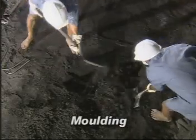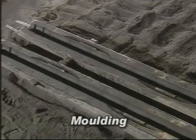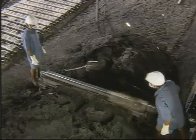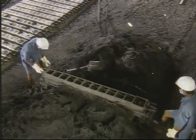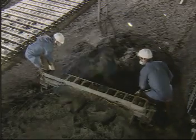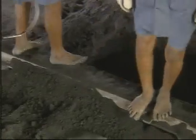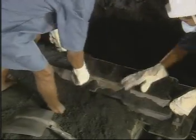The molding bay is first prepared by loosening the bay sand. The molding box is separated in two halves. The lower half is called the drag and the top half is called the cope. First, fine sand is sprinkled on the pattern and the cope is kept over it. The molding sand is filled in the box. This is rammed to compact the sand between the pattern and the box. The excess sand is now removed.